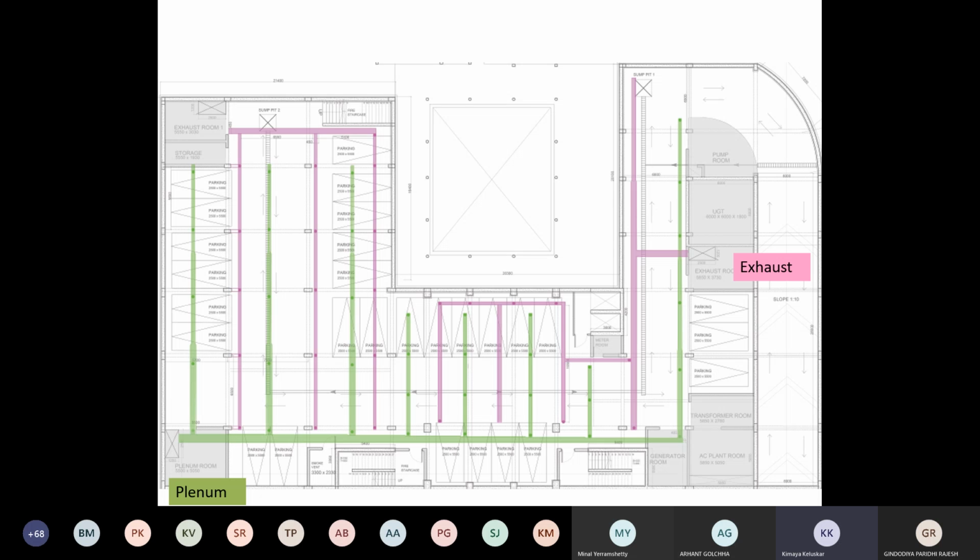Now imagine a scenario where there is fire. The duct will catch that fire and circulate it all over your basement, and within seconds your basement will be on fire. So make sure the ducts don't go through your mechanical rooms, which are much more susceptible to fire. Clear? Is it better?